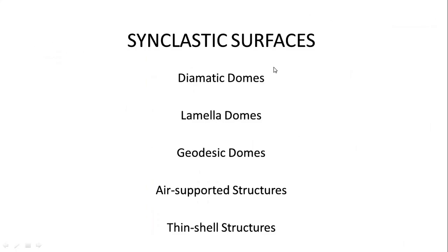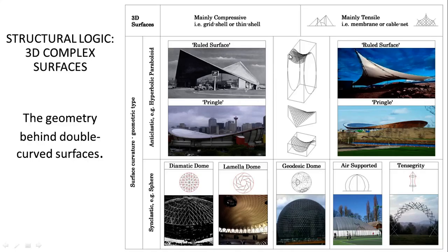Now that curve, if you remember when we were looking at arches, I beg your pardon, I'm going back again. You remember when we were looking at arches that there are a series of curves that tend to work very well structurally, and these can all be derived from a cone, if you recall. And on top of that there is the hanging chain, catenary curves. So you decide what curve it is that you want, and you repeat that curve around the circle. That develops the catenoid.